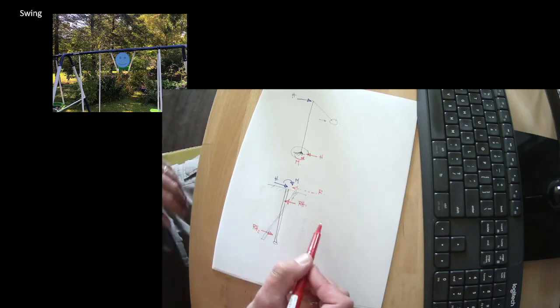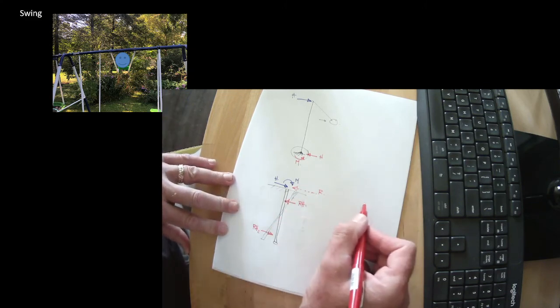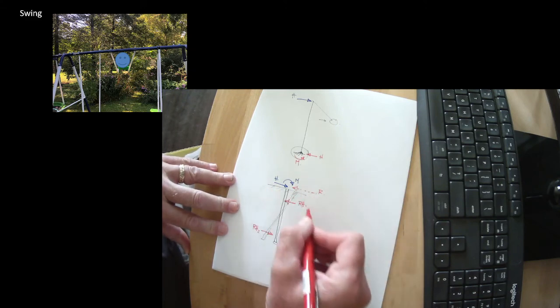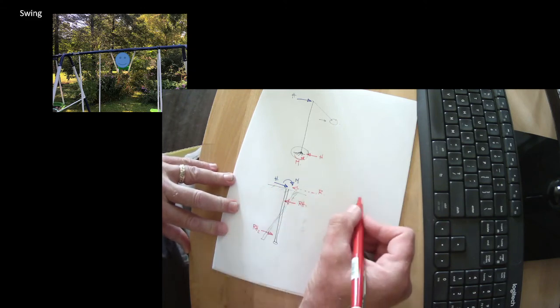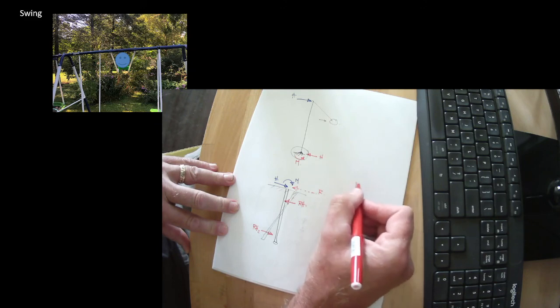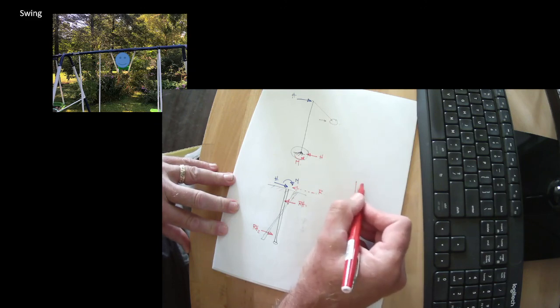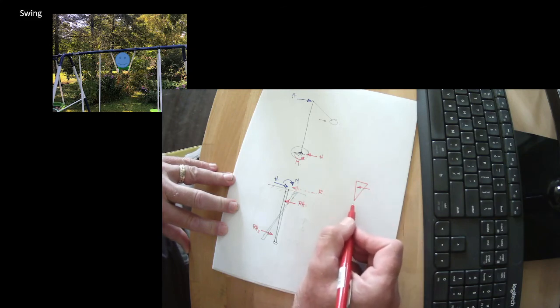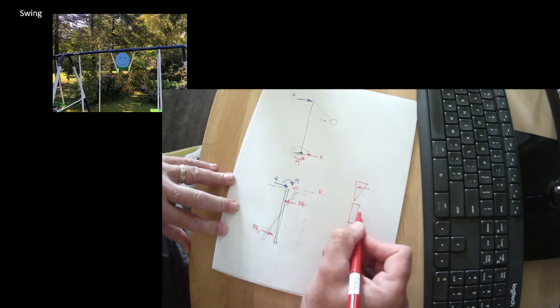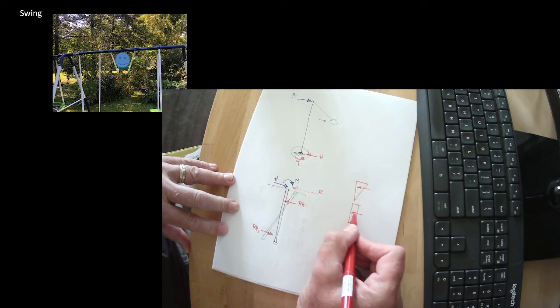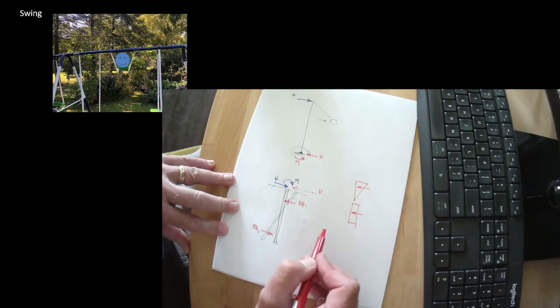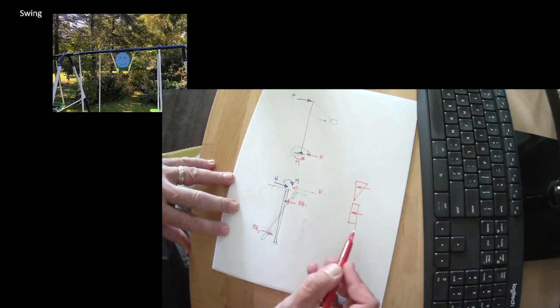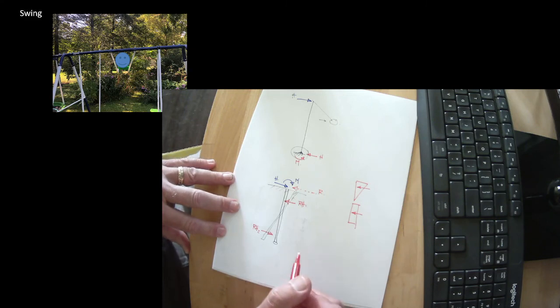Okay, so now we'll think about how can that force be distributed. We already kind of talked about if it's triangular, it's at the 1/3 point. If it's a rectangular block, it's in the middle. If it's trapezoidal, if it's something else.